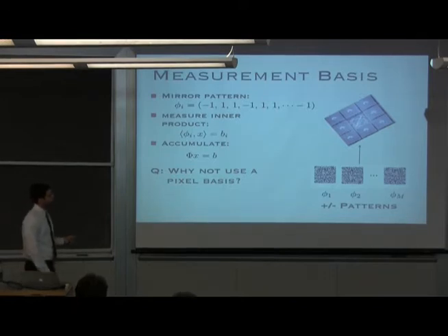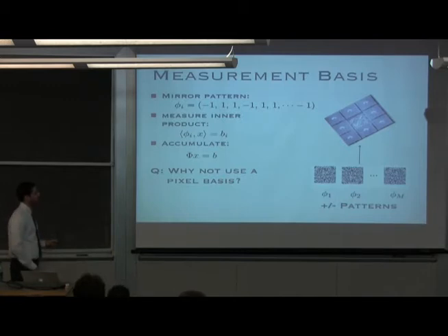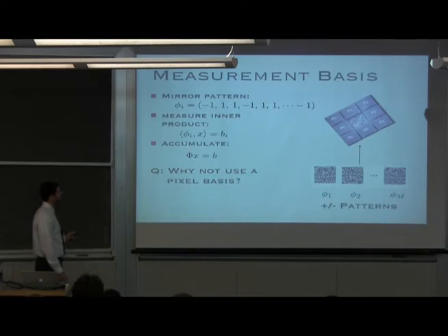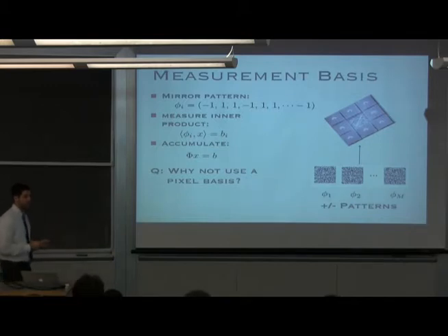And the question is, what advantages does sensing with the DMD give you? How do these imaging protocols work? Every time we take a measurement, we load a DMD pattern onto the device, and what we acquire is, in a sense, an average of certain pixels within the image. Every pixel in the image corresponds to an individual mirror on the DMD. If the mirror is pointed toward the detector, we say that we acquire that pixel with coefficient 1. If it's canted away from the detector, we have a pixel with coefficient -1. So what the DMD is essentially acquiring is inner products of the unknown image x with these measurement vectors phi, where phi is a binary vector of +1s and -1s.